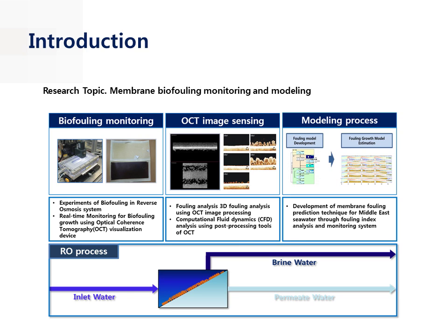In the second step, we deal with the optic device, optical coherence tomography, to analyze the degree of membrane fouling. This OCT device can provide information on membrane fouling in real time without any damage to the membrane or operation. Also, its post-process technique provides a variety of forms of information, such as geometry data for computational fluid dynamics.